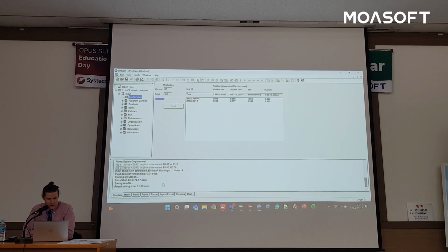If you remember from yesterday, it took 50 seconds to save the results. You saw there was a green row there for a warning, and the different notices that you get here in the log window have different severity. The gray ones are called notices, so they are not that much to think about. Then we have the green ones, which are warnings.